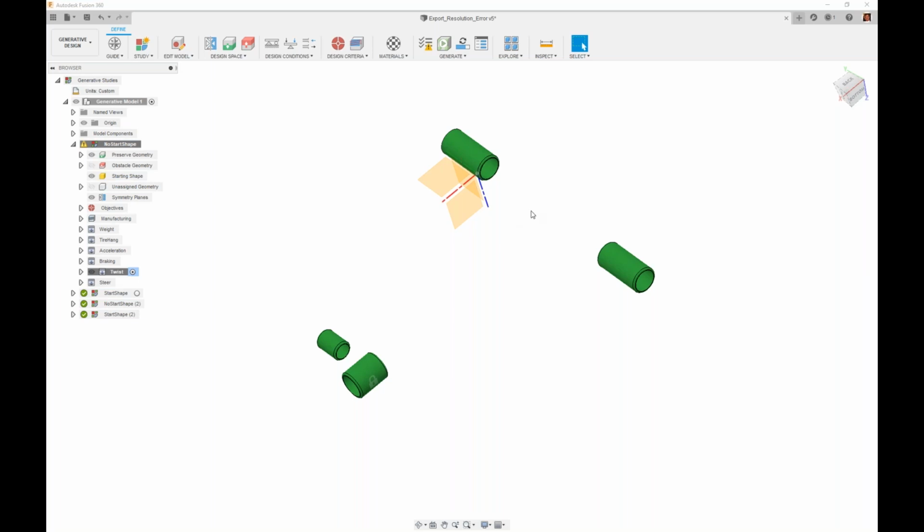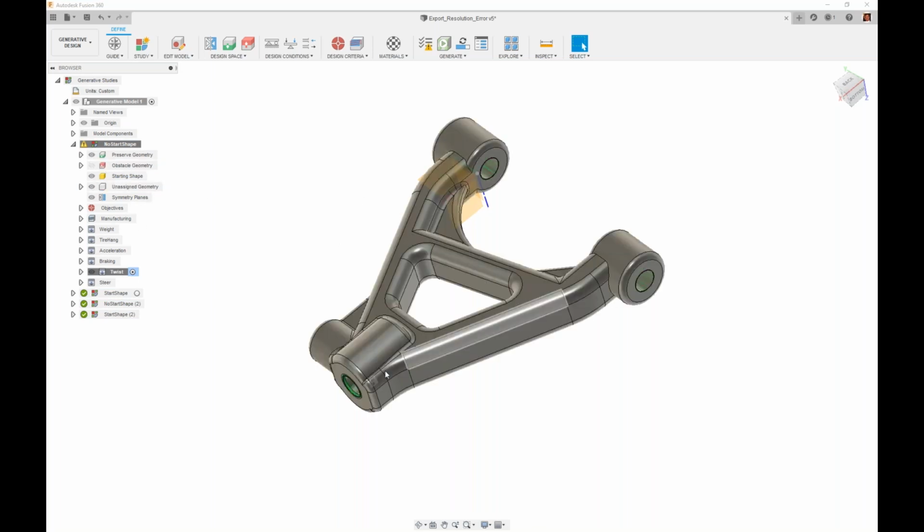In some instances, there can be an advantage to providing a starting shape, whether it's maybe the original A-arm, or in some cases we've done things like a block with perforated holes blown throughout, so that it gives the algorithm a number of different surfaces that it can start moving rather than playing with just the outer boundary. Each of those has a given level of effort, but each has the ability to have a different impact on the final solution.